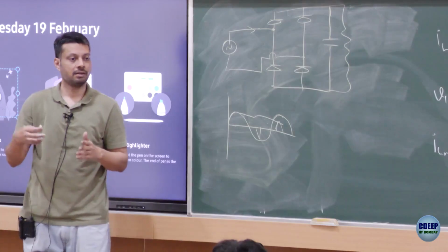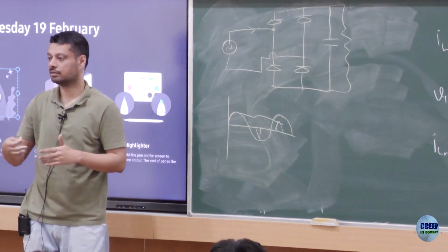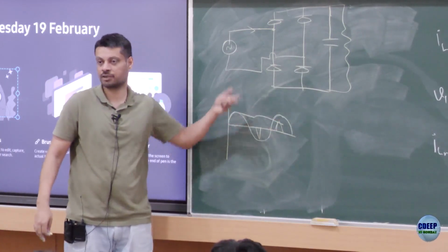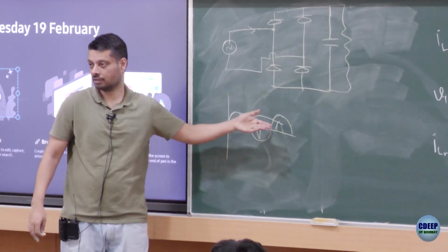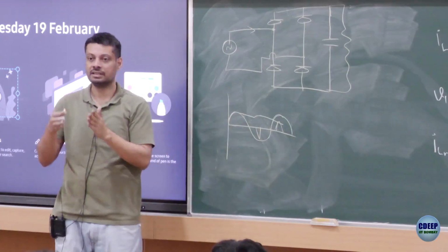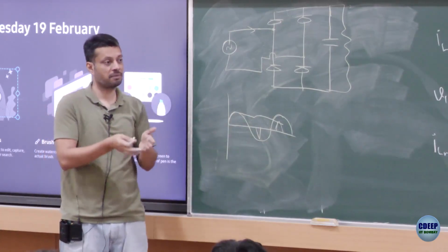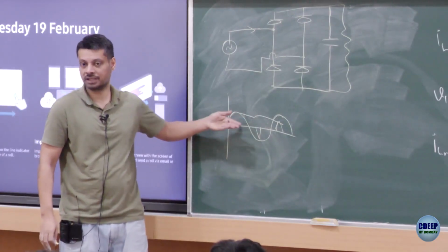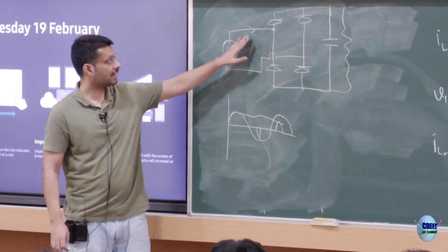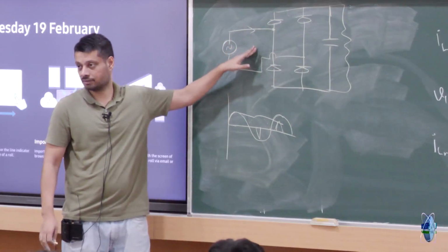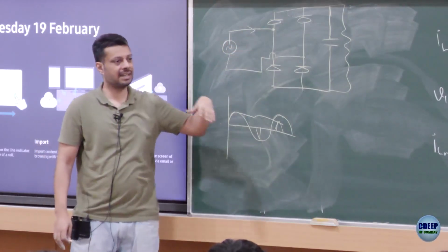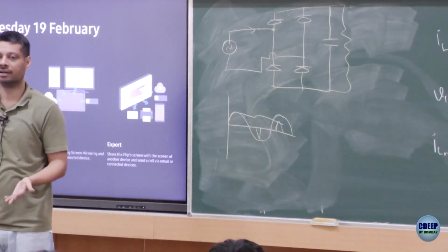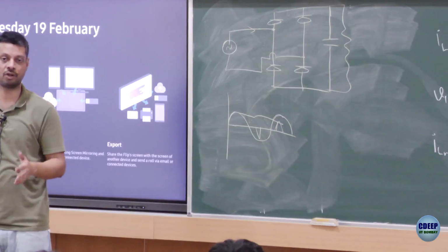after pi, right? So if you shift it and you invert it, you will get the same waveform. That is what it means, right? Half-wave symmetric means f of theta equals minus f of minus theta. That means if you shift it by T by 2 and you invert it, you will get the same waveform. So the current that you draw here is half-wave symmetric, and that is the reason I am saying that most of the currents and voltages in the power network would be half-wave symmetric. Most, not always.